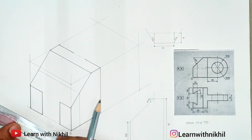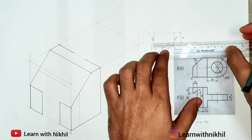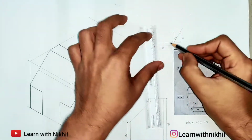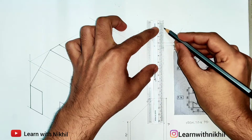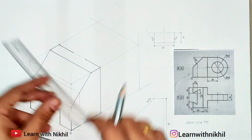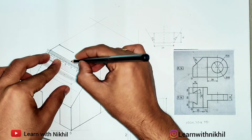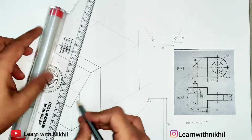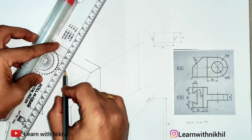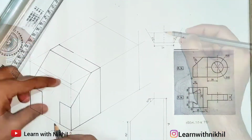So before plotting we will just mark the center point line. As it is at the center, I'll just mark the center line. So this is 30, so the center point will be at 15 millimeters. So from here I'll just mark the center line. Now the same I'll plot it here. So the half of this is 3.5. I'll take this as the parallel reference line. I'll draw a line here. So this is totally divided into half, and it is divided on the slant line as it is cut on the slant part.